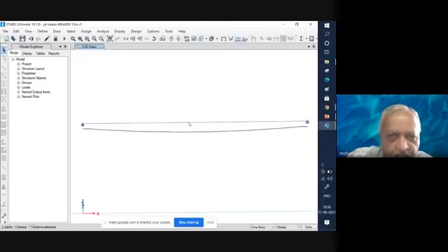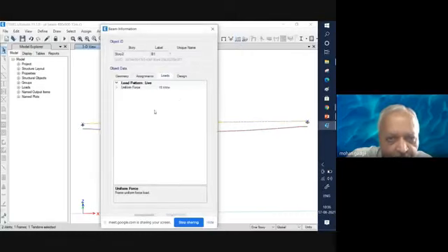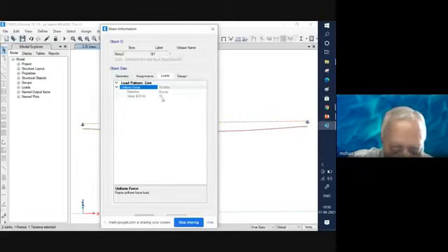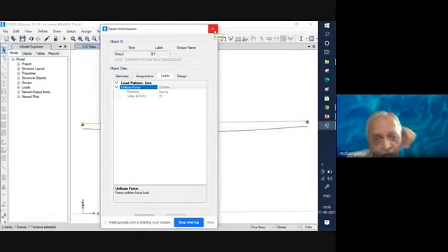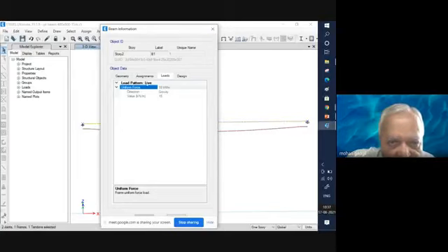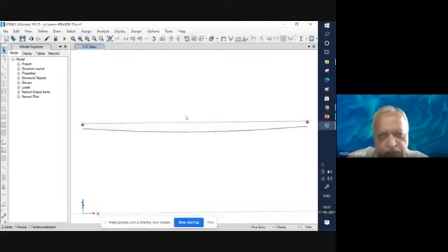So on this member, I have applied the load. If you consider this load, I have considered this load as 15 kilonewton per meter in addition to self weight. I think earlier I have indicated 25, but actually I have applied 15 kilonewton per meter, or was it 15 only? Okay. Now I have taken the superimposed load on it as 15 kilonewton, that is taken as live load. The self-weight of the beam is already part of the load itself. So I have self-weight as a dead load, and I have this live load applied on it.